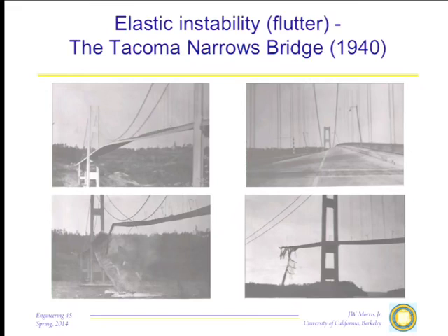You see, the thing about natural vibrations is that unless you really blew your design, you are talking about instabilities in some harmonic, some complex vibration, which in ordinary circumstances you'd never see. If you build an engine and you test it and it's rattling all over the place, you say, hey, I've got a problem. What you've got to worry about is you build an engine and you test it, and the rattle is a natural displacement of 1/10 of a millimeter. You're never going to see it, never going to notice it, nobody knows it's there until the right impulse comes along, which is just dead on the natural frequency of that 1/10 of a millimeter, and suddenly it becomes half a foot, and there goes your engine. So that's the reason it's such a difficult thing to handle.